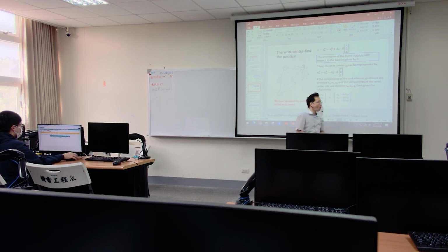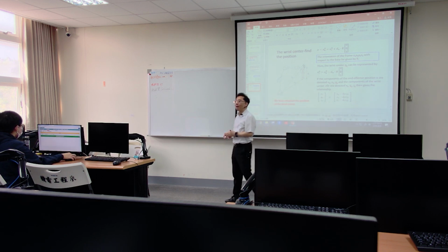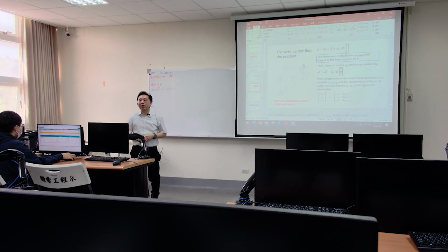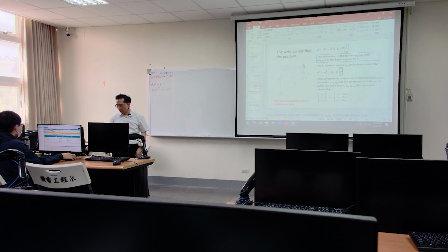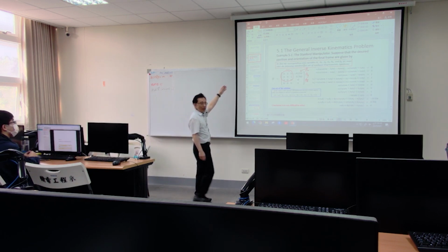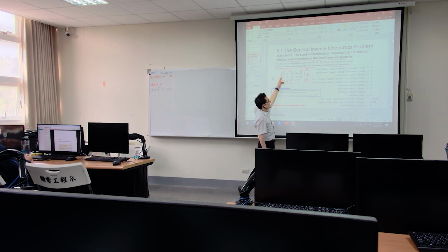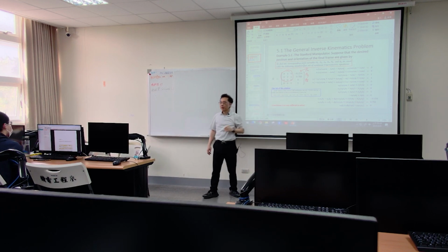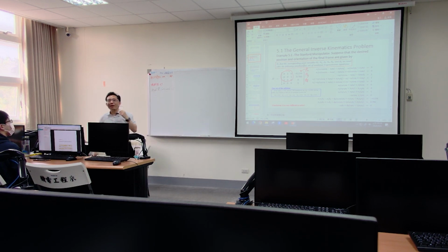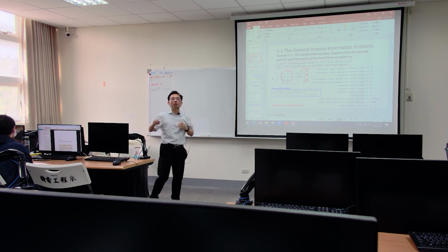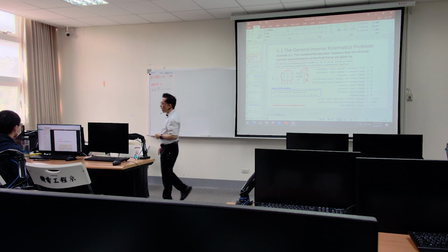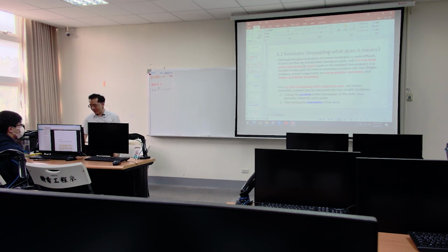But how about R13, R23, and R33? It is a vector, and it is also provided in the information I give you. For the first page over here is the rotation matrix, or orientation matrix. So for R13, R23, R33, you need to locate where they are in the matrix. Then you need to adopt the values into our equation to find the wrist center.